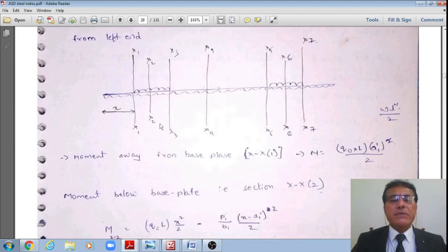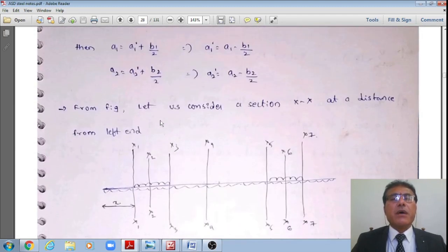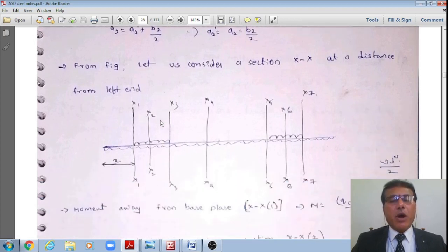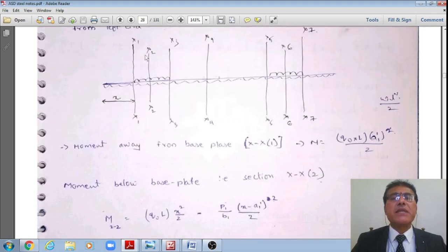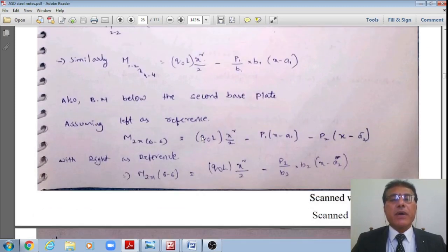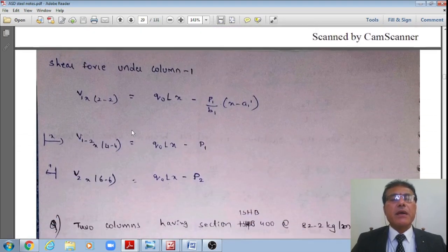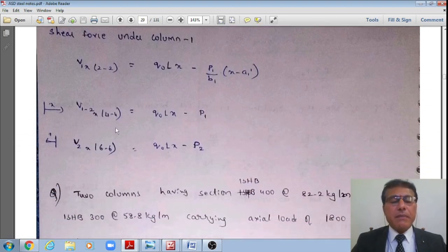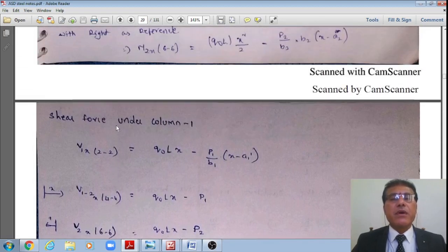This is how I have explained elaborately. You may just go through that. Whereas for the analysis of the bottom tier grillage, it is also analyzed at different sections. At section 2-2, by equating the shear to 0, I get where I'll be getting the maximum bending moment. Therefore at that section I'll find out the maximum bending moment, for which I'll design. You may just go through this for further discussion, students.